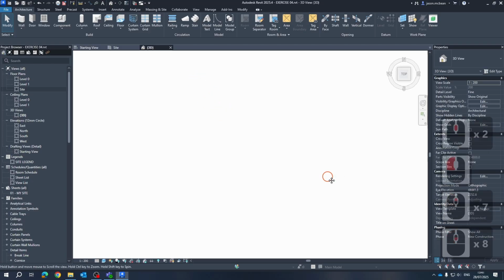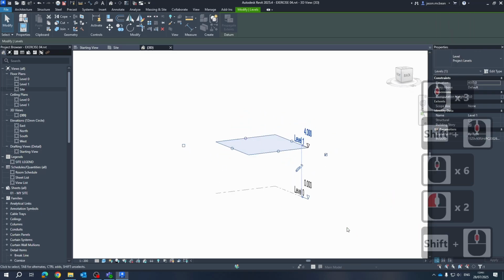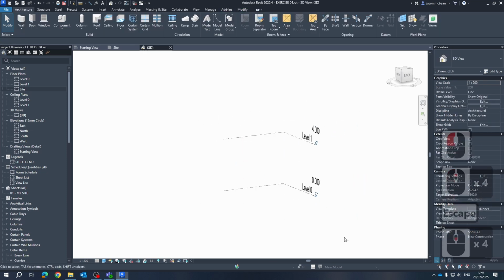You should all know by now that in Revit, if you go to 3D view and we're still looking at our site origin, you will notice that we get these levels. If you're working with topography and external works, we've got driveways, there's a whole lot of additional levels that you have to add, and sometimes they will start polluting your building model. So typically we build a building model separate to our site model and then we plug them together. It depends. Small projects you can keep everything integrated, but when projects get larger you have to separate it. The workflow will depend on the level of detail that you need to achieve and the complexity of the project.